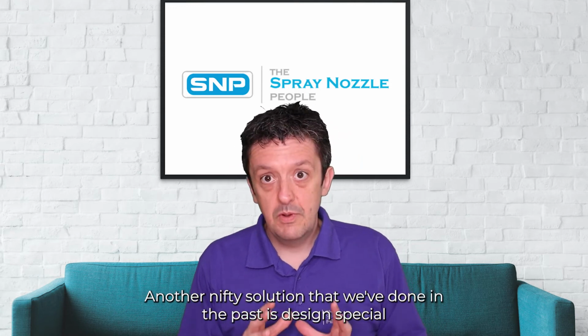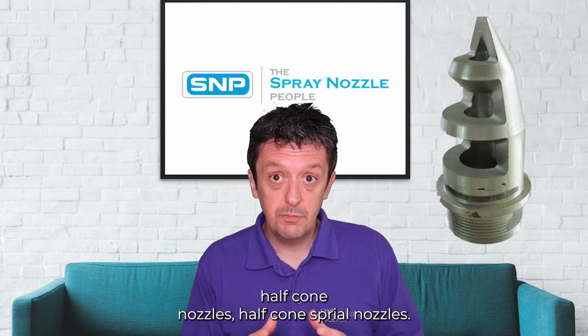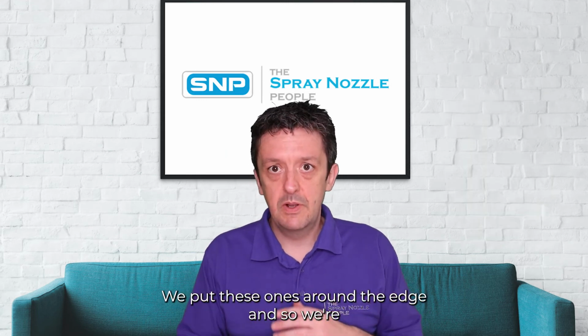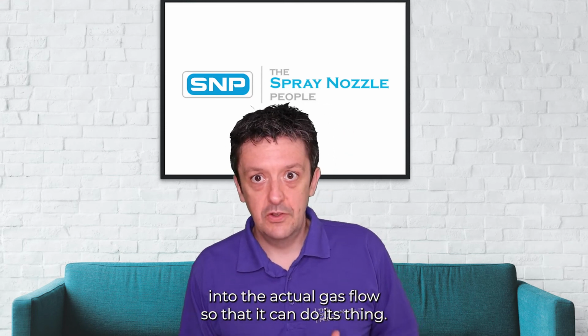Another nifty solution that we've used in the past is to design special half cone spiral nozzles, which produce a semicircle of spray rather than a circle of spray. We put these around the edge, so we're getting less water on the walls and more of that spray into the actual gas flow so it can do its thing.